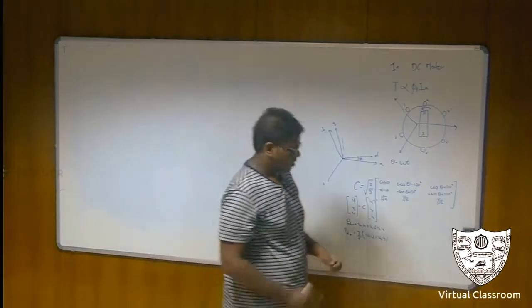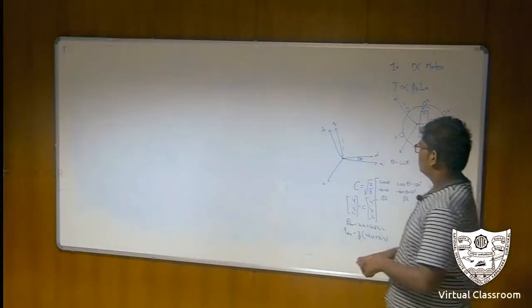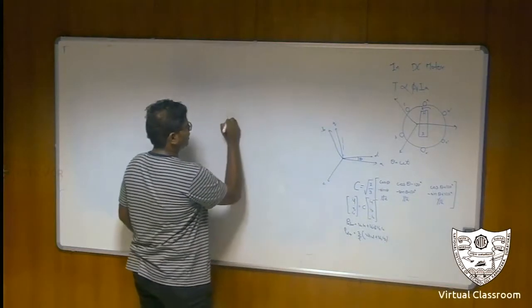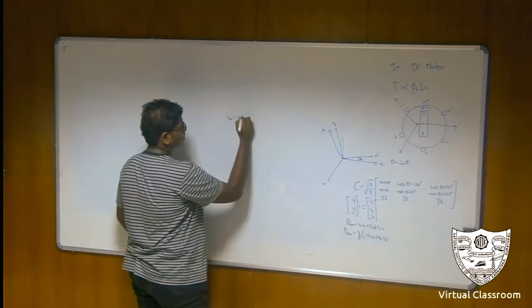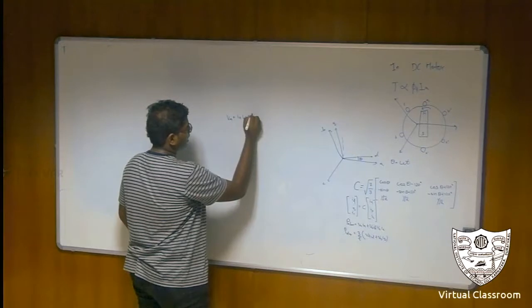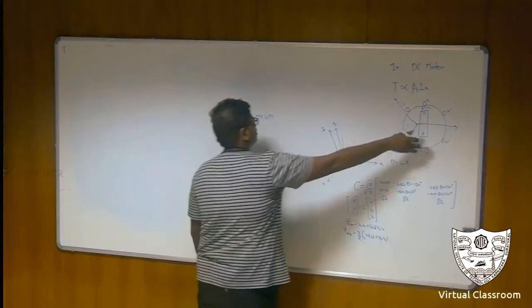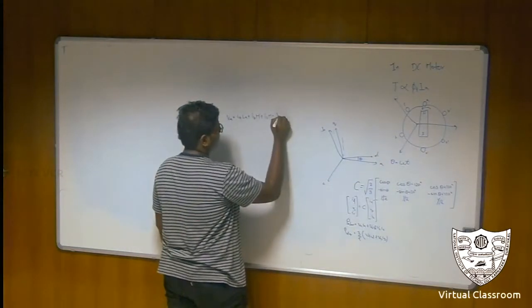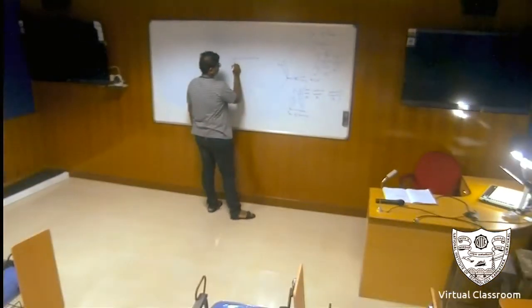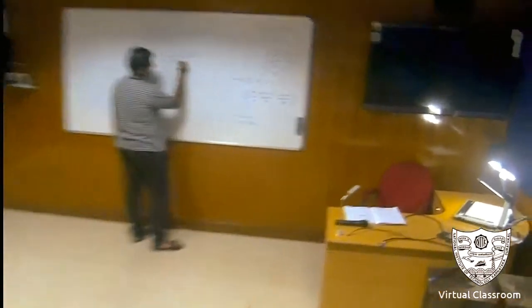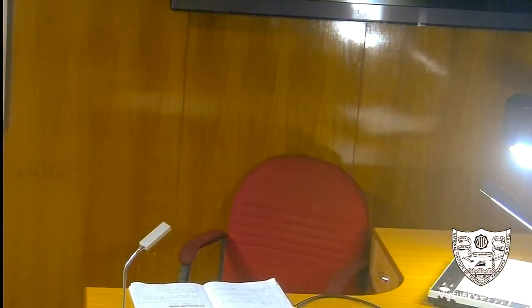For a permanent magnet synchronous motor, in each phase I can write Faraday's law. VA will be equal to IA LA plus IB into M plus IC into M plus the flux due to the magnet, that will be some lambda MA. Similarly, VB will come out as IA into M plus IB into L plus IC into M plus lambda MB, and so on.